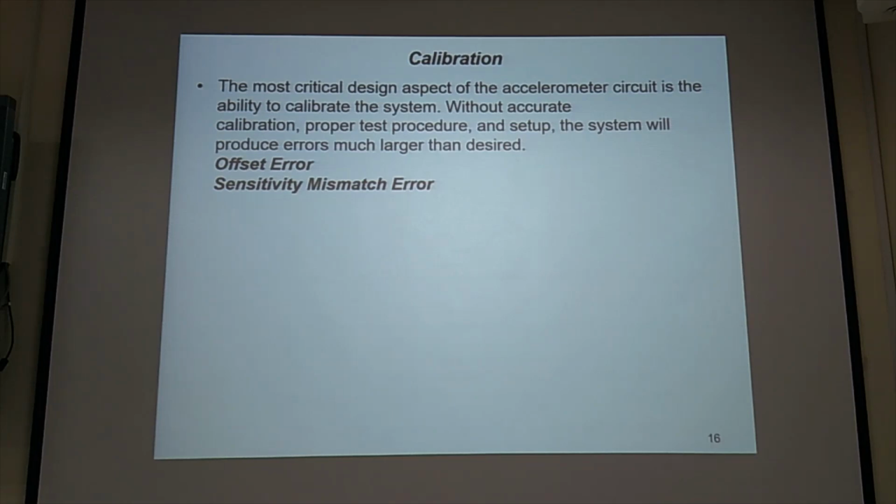The input resistance multiplied by the input bias current gives the input bias voltage, and this is the offset. Then the offset will go to the output even without any acceleration, due to the input offset voltage.